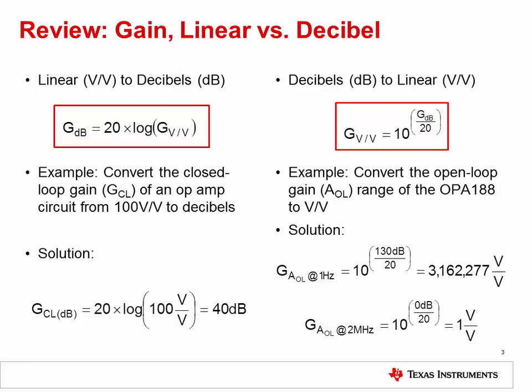When working with electronics, we often need to express quantities such as op-amp gain, signal-to-noise ratio, common mode rejection ratio, and power supply rejection ratio, whose values have large spans. Therefore, it is important to have a mechanism upon which we can represent a large range of values while using small numbers. This mechanism is called the decibel, or dB for short. Note that decibels have no units.